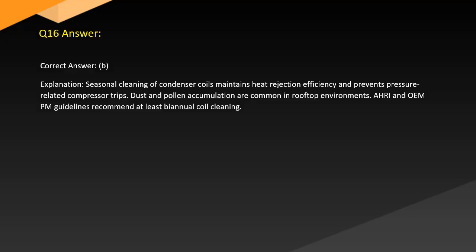Answer. Correct answer: B. Explanation. Seasonal cleaning of condenser coils maintains heat rejection efficiency and prevents pressure-related compressor trips. Dust and pollen accumulation are common in rooftop environments. ASHRAE and PM guidelines recommend at least biannual coil cleaning.